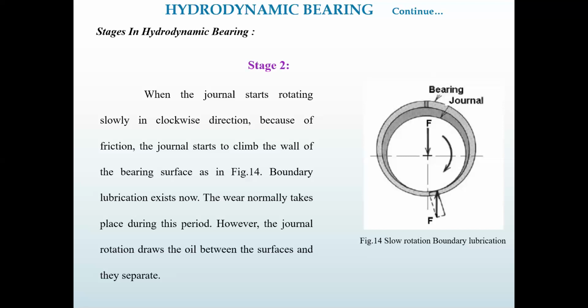The shaft, or journal, tries to climb over the bearing, and because of that pressure is created in the oil, that is called a hydrodynamic action. And because of this hydrodynamic action, the layers, because the journal is trying to climb the layers, so as this climbing starts, pressure develops.